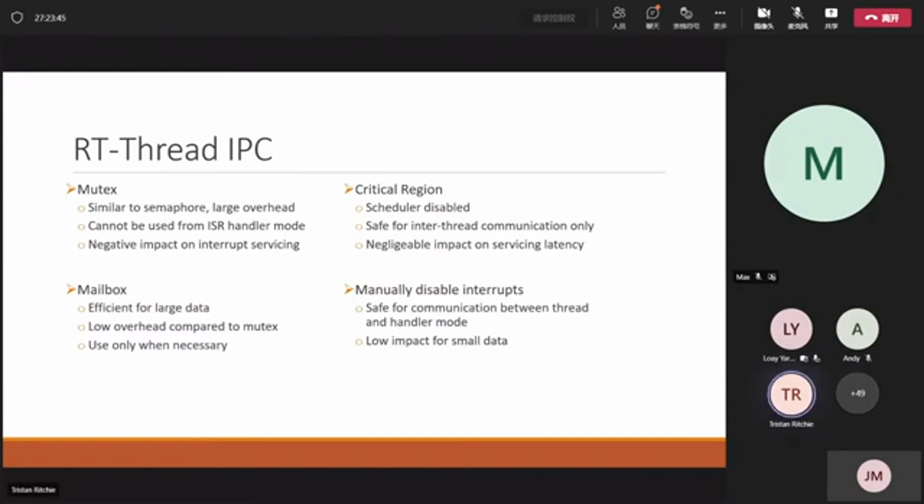For this, we should simply manually disable interrupts. This has the effect of disabling the scheduler, but also disabling other interrupts, so it cannot be preempted. And this will, of course, avoid any spooky behavior when it comes to a shared memory resource.